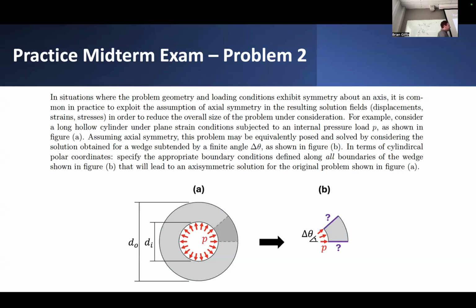But you'll notice the P that we're applying on this interior surface, it's compressive. It's pressing into the surface. So what does that mean if we were going to try to relate sigma RR to this applied pressure load? Equal but opposite. Yeah, given the sign convention we've chosen for our stresses and our chosen coordinate frame, and assuming that P is this outward radial pressure, we have to say sigma RR is really just equal to minus P.